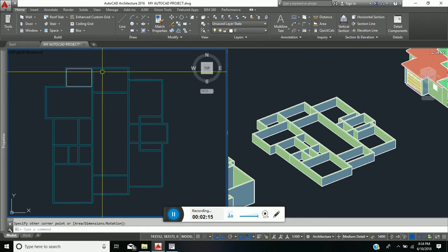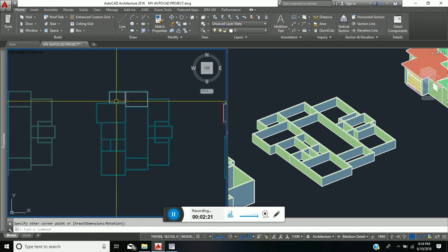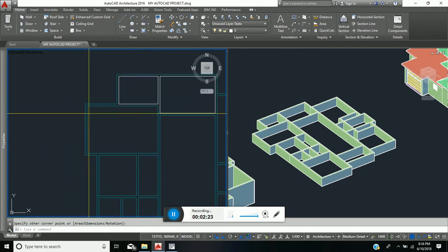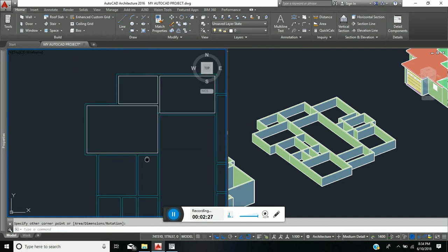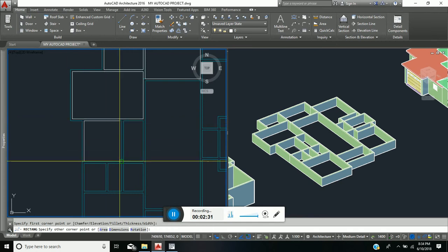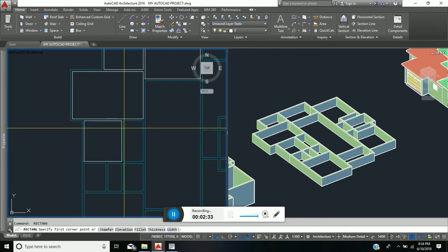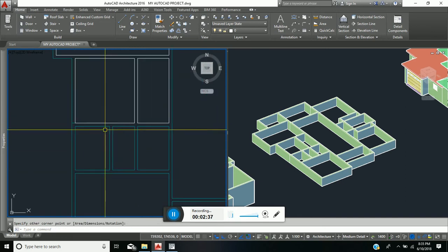In other words, what we want to do is to achieve polyline in order to offset our foundation width. And so rectangle is the quickest polyline to cover all lines. And so all rooms that are rectangular in shape, I'm going to be giving a rectangle on each.